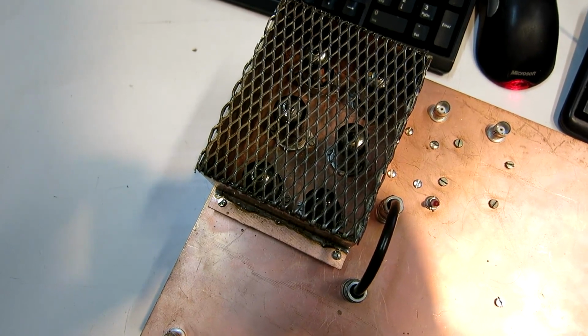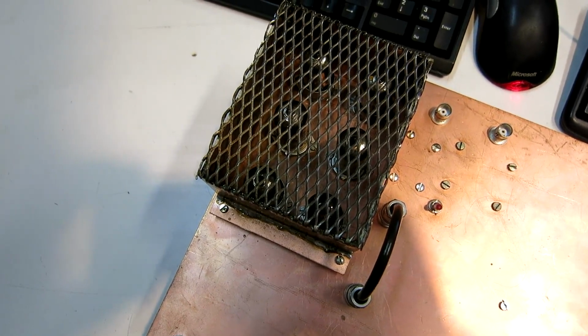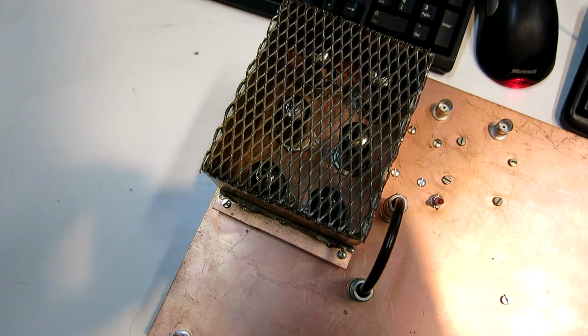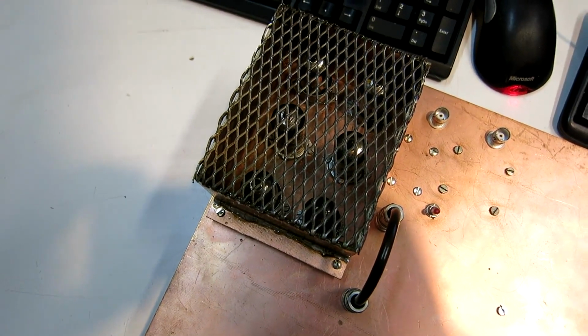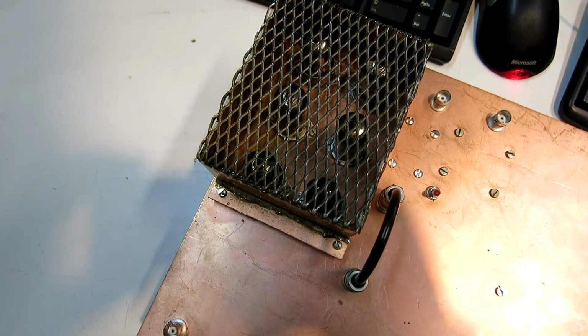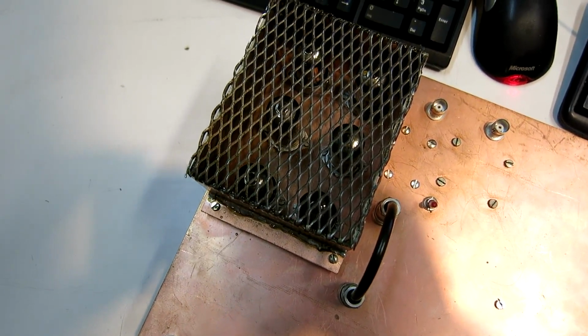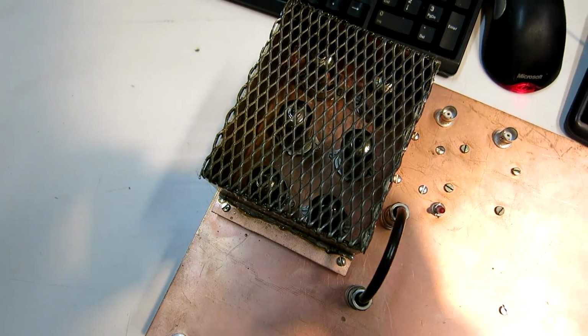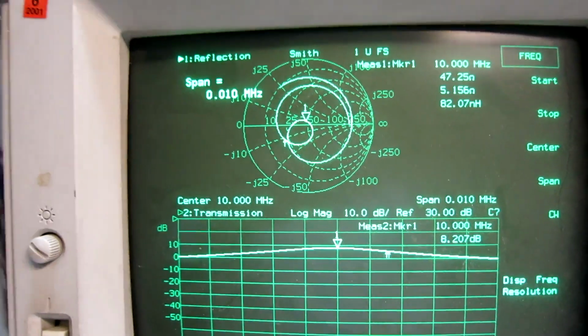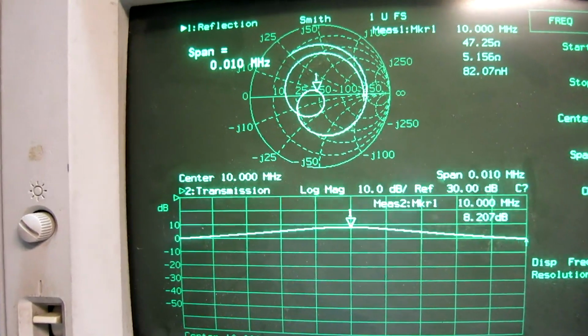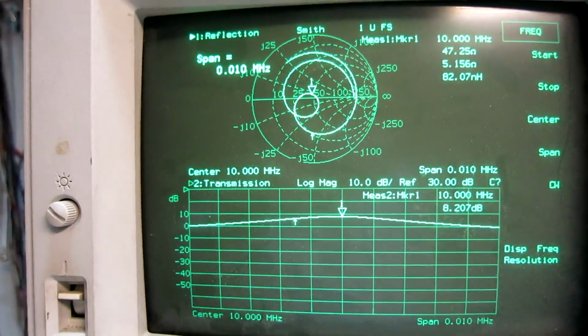So the input impedance on the cathodes, all the 12 parallel cathodes, is low enough to fit the impedance of the crystals. And it runs at a fairly high power, and there are no parametric effects possible in this. The vacuum tube amplifier has a crystal filter.